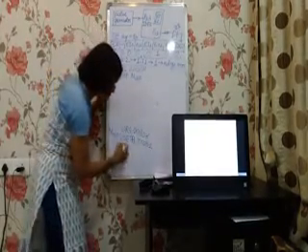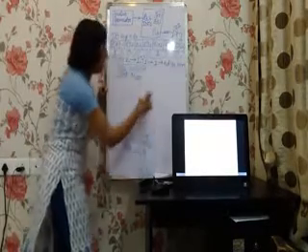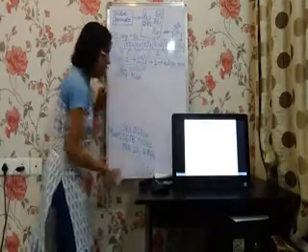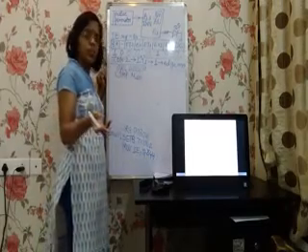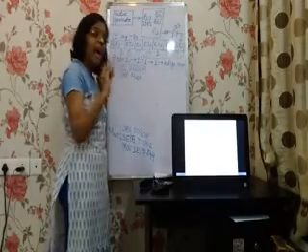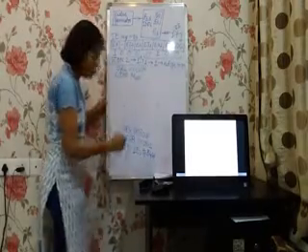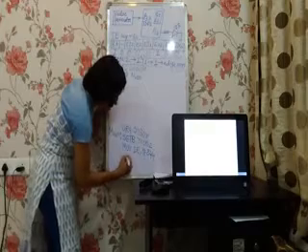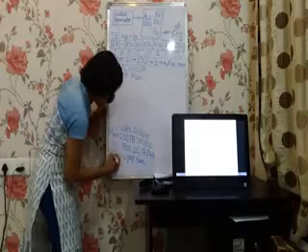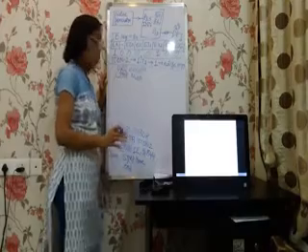Next, what you have to do? Configure the IE register. We have already taken the value of IE. IE comes as 84, so I give 84H. What else do I have to do? Nothing. In the main program, I only have to inform that INT1 is defined as edge triggered and we are doing programming using interrupts, so enable INT1. These two things we have to do. And then here I will give SJMP here, at the same instruction, followed by END. This is my main program. Now, where will my subprogram start?